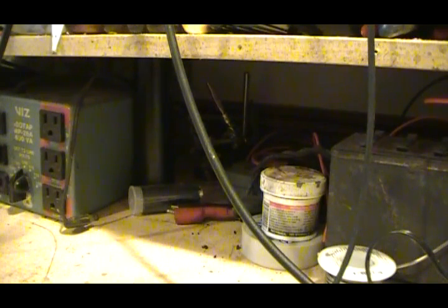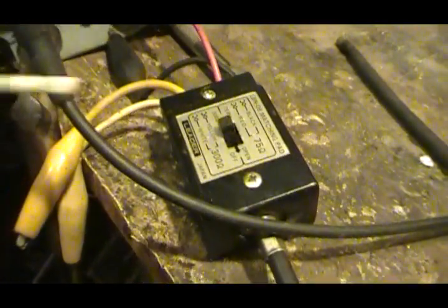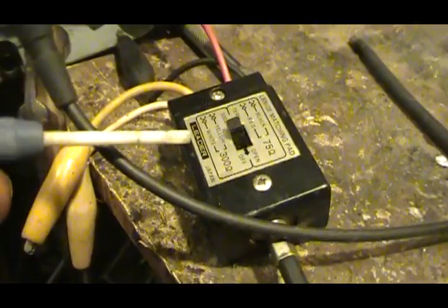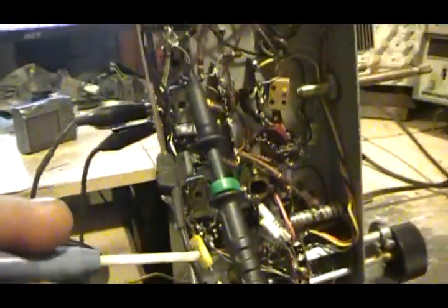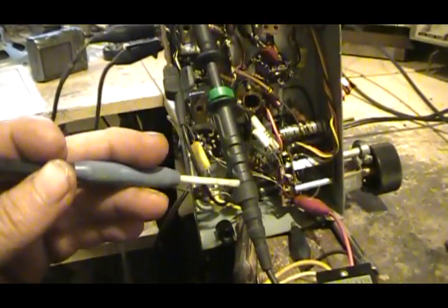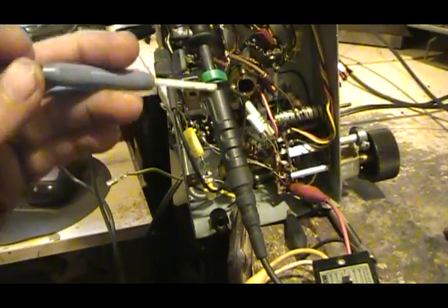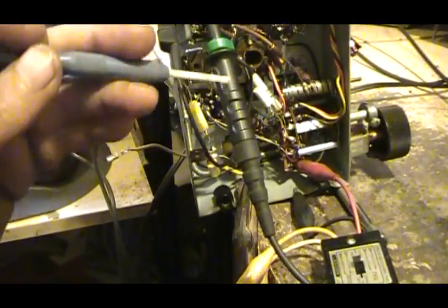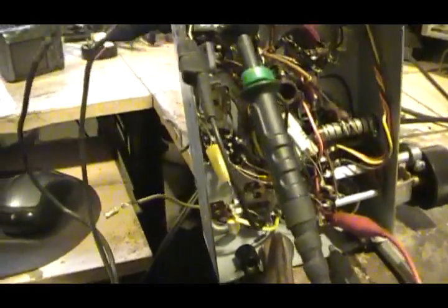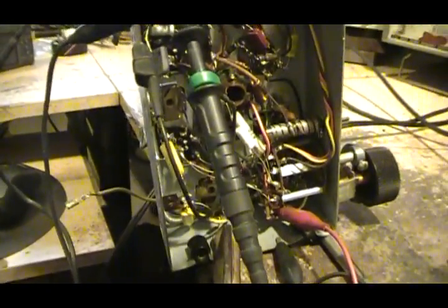I'm not using what they require on here. They talk about using a special filtering, but with the way I'm feeding the RF in, this little box here has its own filters in it, which basically are the same thing that they're requiring. And then I'm using the DMOD probe, and it seems to work better without the 1 meg resistor, and I think that's because it's got pretty good high impedance on its own, so it doesn't really need it.